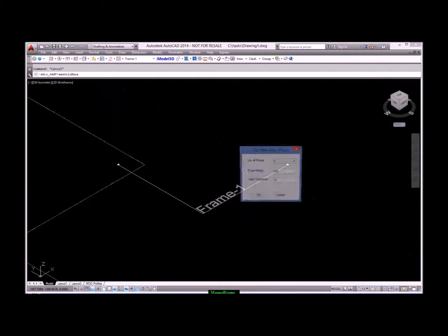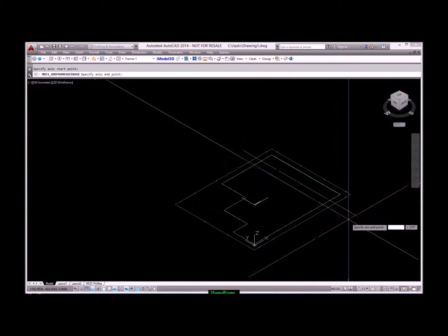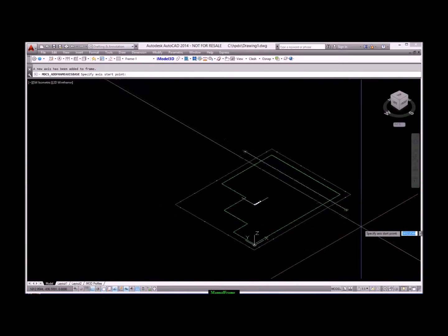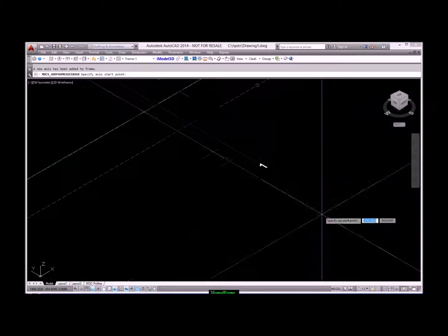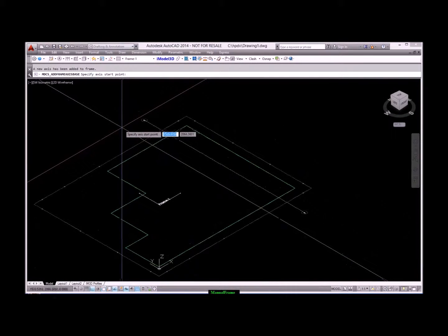This command allows you to draw a single base frame axis. It creates the base for a frame 2D which will be used to draw frame elements such as columns, beams, walls, girders and braces. As mentioned above, having these elements lie entirely in a frame 2D plane is crucial to the analysis. The following dialog box will appear as a result.